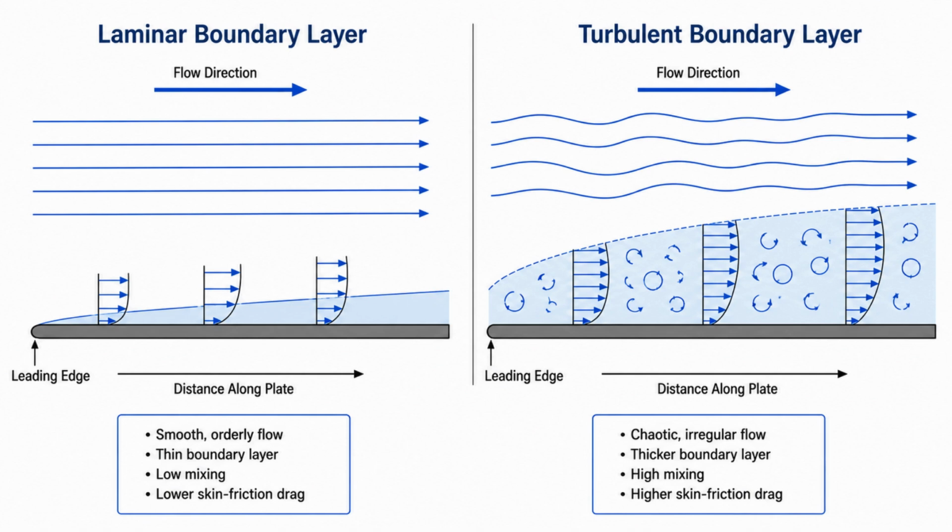In a laminar boundary layer, the air moves in smooth, orderly layers that remain nearly parallel to one another. Because there is very little mixing, laminar flow produces relatively low skin friction drag. This makes it highly desirable for improving aerodynamic efficiency. However, laminar flow has one important weakness. It contains relatively little energy near the surface, making it easier for the airflow to separate.